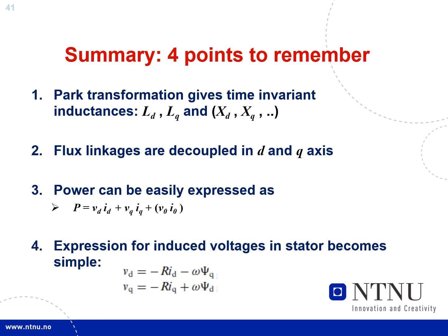It makes the LD and LQ, etc. The flux linkages are decoupled in D and Q axis. Power can be easily expressed as the product of voltage and current in each axis. And the expression for induced voltages in stator becomes very simple as shown here.